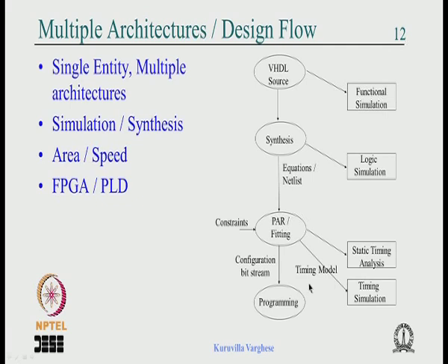And most of the component vendors, the FPGA or the PLD vendors, they have separate tools but they give an integrated GUI from which you can call the individual components using the graphical user interface. So it is convenient, but they also allow you to write some kind of shell script to use it separately so that you can run it without the GUI, because when you have a complex design it may not be very convenient to sit in front of a GUI and start clicking many selections.